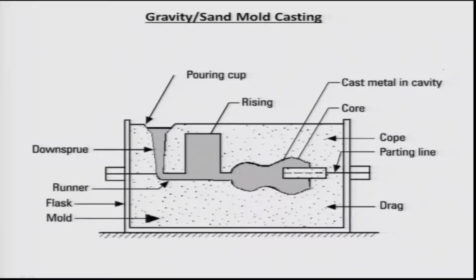The liquid which is poured in the pouring cup travels to the cavity and then starts solidifying. And because of the sand mold, the walls of sand act as heterogeneous nucleation sites. And once the nucleation happens on the surface or the walls of the mold in which sands are present, the solid grows into the liquid. So our objective in the phase transformation of solidification is to understand how the nucleation happens, and how the growth followed by it can be understood.